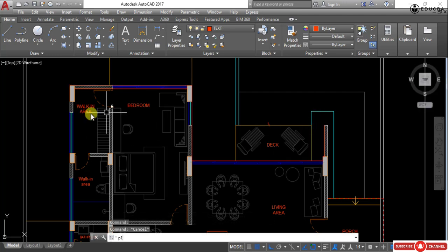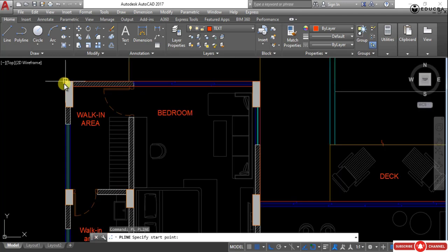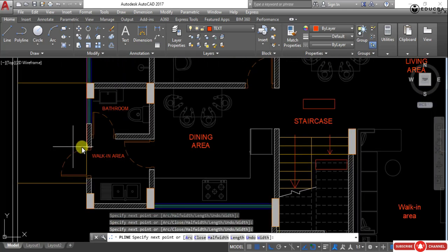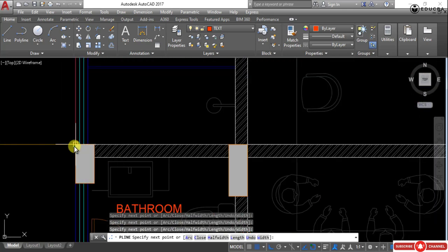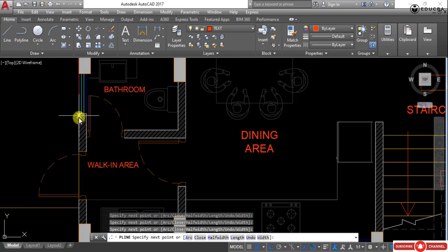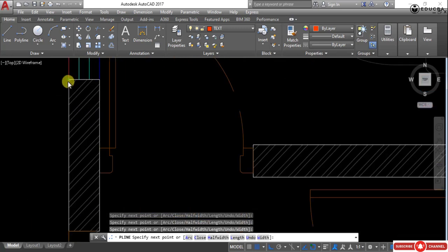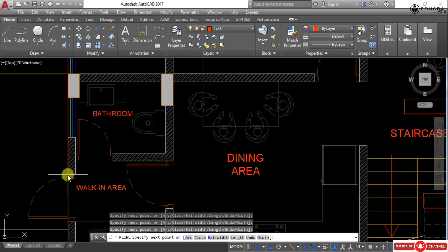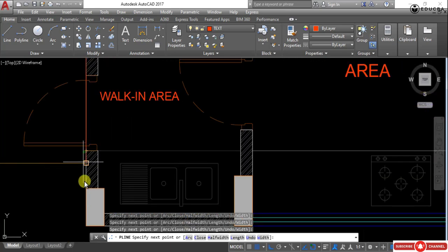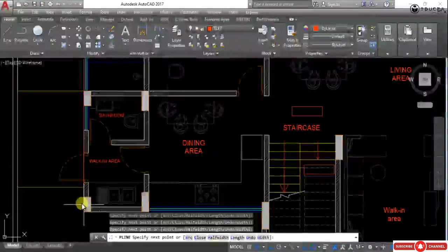We are going to extend that line again. We are going to use a polyline command and move to the points which have junctions or starting or ending of the openings in the wall. We are going to fast forward this sequence so that you understand and do it yourself.